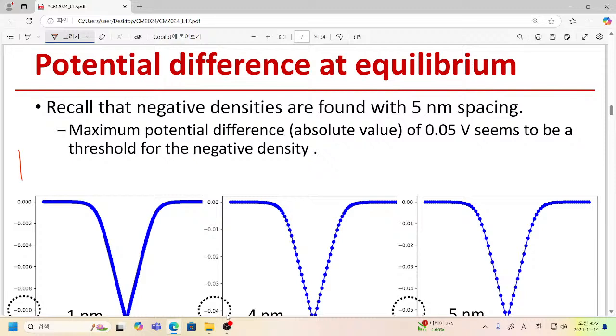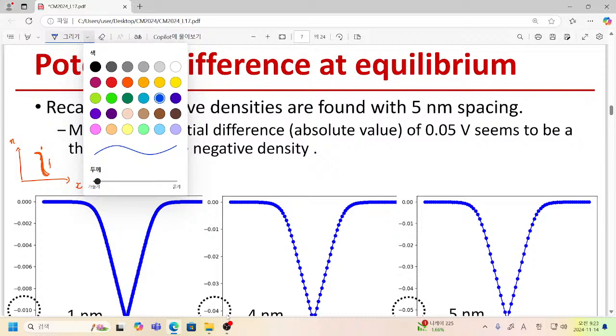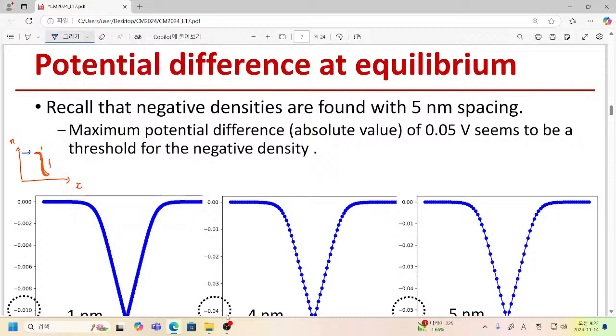If you have high doping density, then you can easily understand, so if this is position and if this is electron density, then you can see that this depletion region becomes nearly narrow. However, more or less when we have a certain change, so if we just draw potential, then there will be certain difference corresponding to the doping of our p-type region and n-type region.